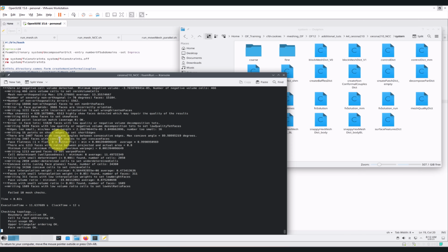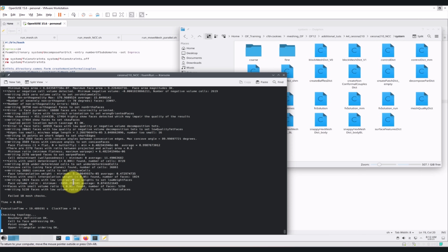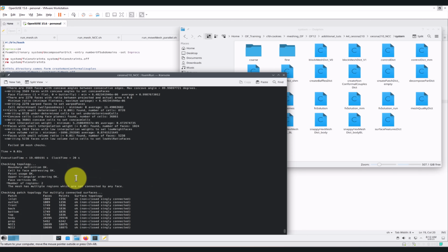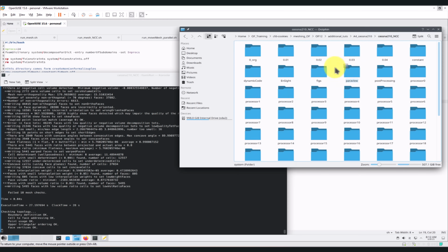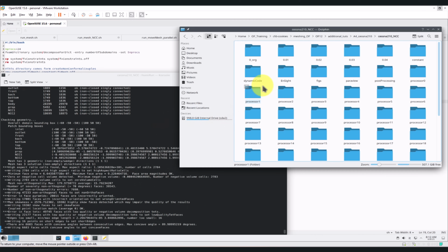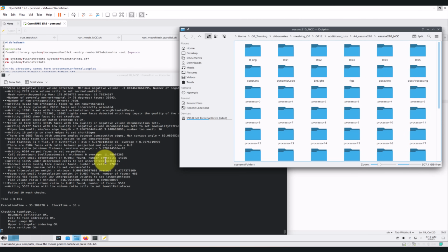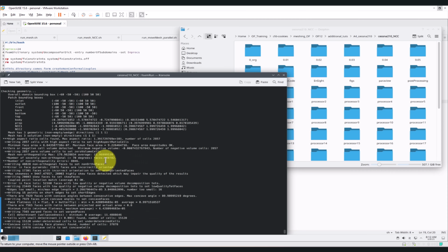By the way, I will also comment on something now that I have checkMesh at every time step. So it is running, but eventually it will crash. The mesh quality will be too bad. It's already super bad. But at one point it will do a super crash, because when I move in here, those two patches and the regions are still connected. I haven't done the topological separation.